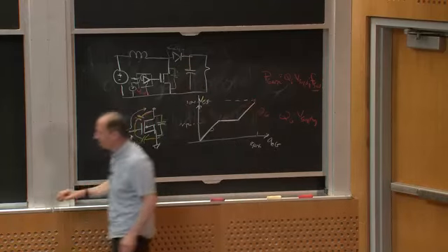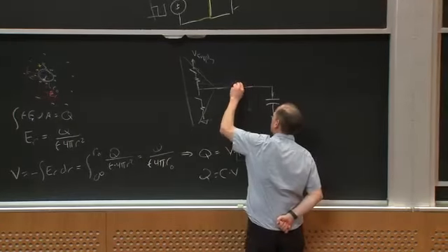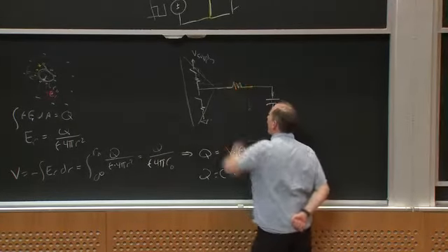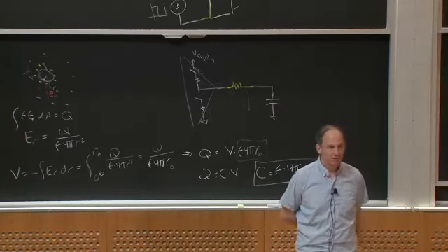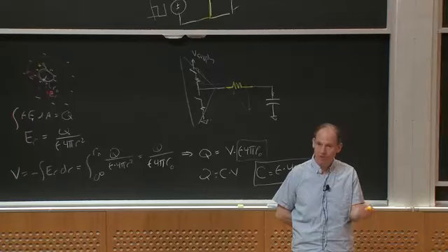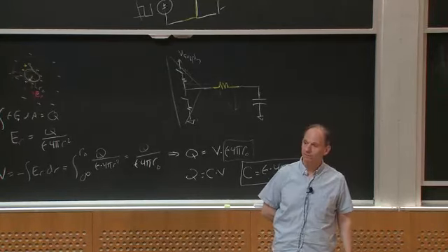So a lot of the time, we actually put additional resistance in here to slow how fast I turn on the device. And some gate drivers will tell you what that is. Sometimes you put in a discrete resistor to do that.